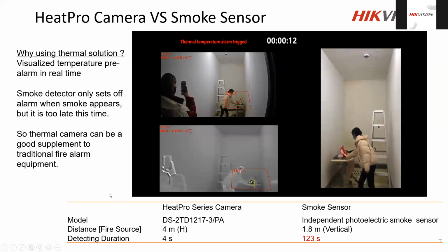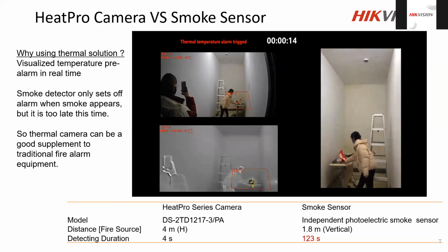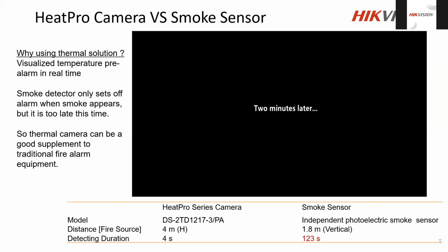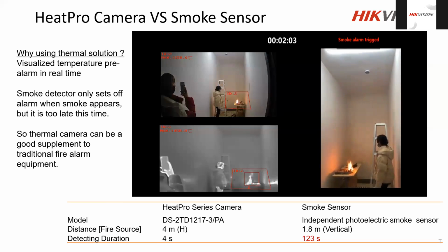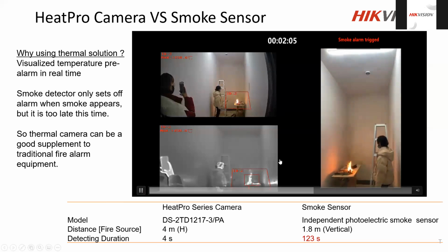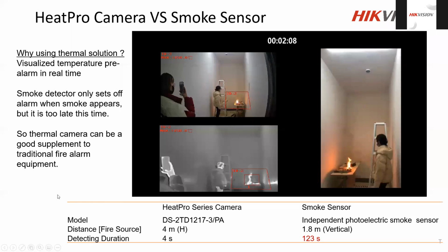Already our temperature camera has picked up the fire, but you see only 2 minutes later the smoke alarm is triggered. So this is the beauty of using the temperature camera, where you can have faster results.